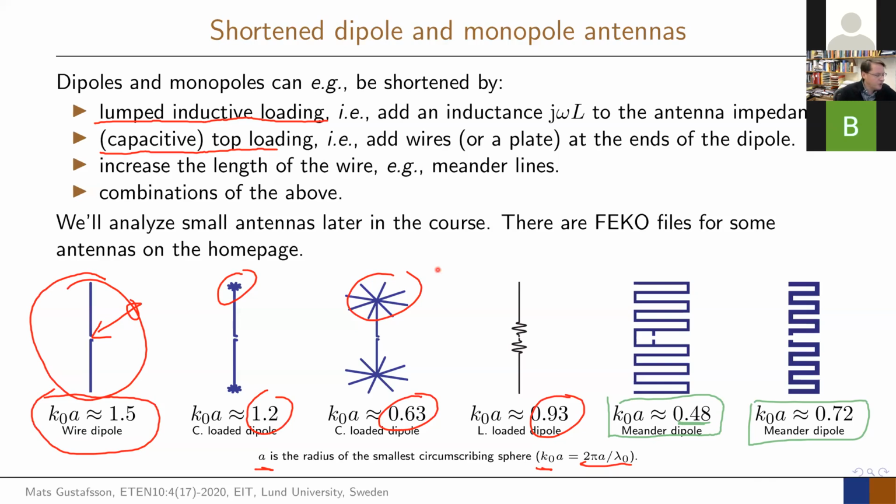If you think about your cellular phone antennas, a half wavelength would be like 20 centimeters, and then if you do a lot of folding, you're down to like 7 centimeters, and it actually starts fitting inside of these kinds of devices. So you start playing around with these structures. What you do with the meander line is basically increase the length of the wire.